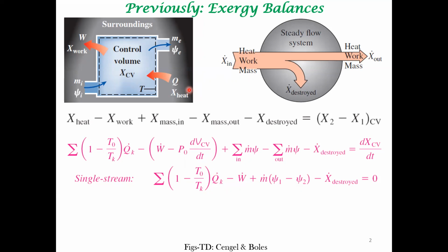I always say that exergy is the other side of entropy. If you want to understand exergy well, you should also understand entropy generation very well. Exergy destroyed is closely related to entropy generation.